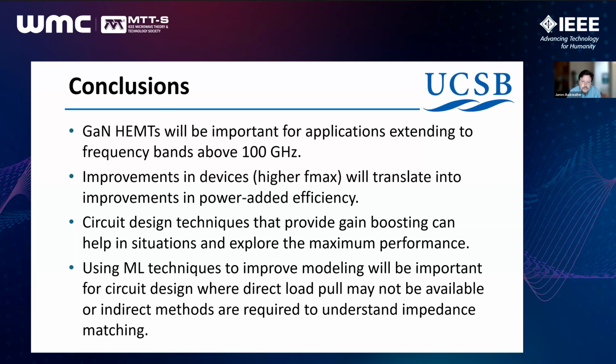And as circuit designers, that's what I'm most interested in, taking that device and getting the most power added efficiency. We explored embedding networks here, and I hope you have an appreciation for that topic. They're useful for gain boosting, but I think more generally, we'd like to see that field of embedding move towards multi-constraint optimization, where we're getting high power density, high output power that matches the power density of the device, not just gain boosting.